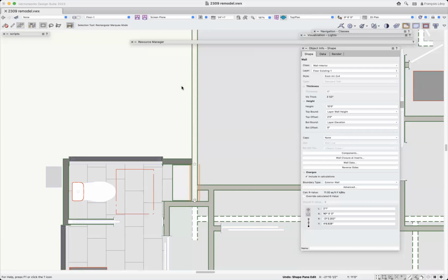Of course, it assumes that all of your walls are 2x4. They may not be. You may need to change that component thickness, or turn it to an unstyled wall and change its depth or thickness and so forth. But this way, you don't have to go through the trouble of like taking your wall, deleting components, changing the class. All of that just happens in one fell swoop simply by changing the wall style and lining up those components.